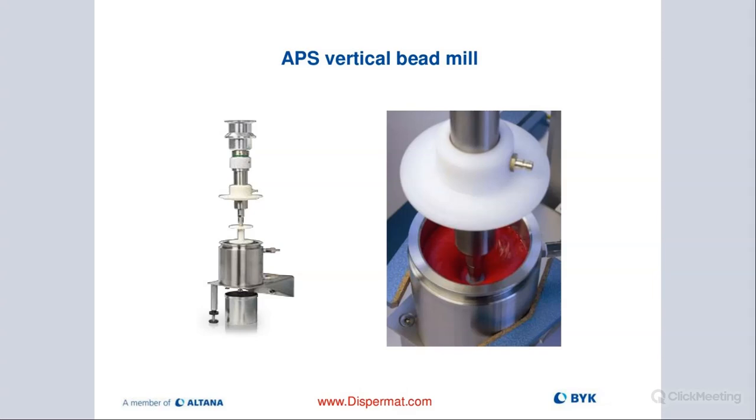And then we hook up an air hose. You can see on the right picture, there is a socket. That's where we actually hook up our air hose, and then we can purge our mill base out of the container with air pressure into the container right below. And that actually is a very beautiful, effective, quick way of milling relatively small volumes.